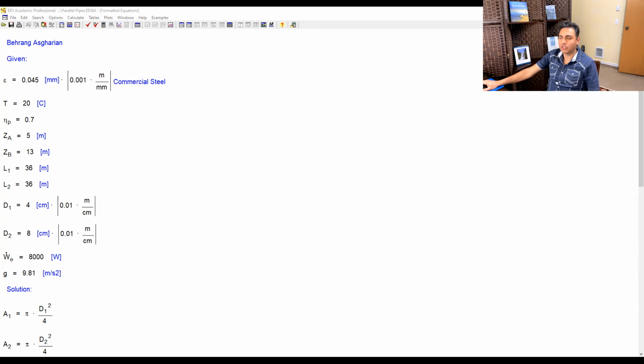That's maximum. You never get friction factor 10 or 11 or 15 in turbulent flow. In laminar flow, you can get a value like that, but never in turbulent flow. That's crazy. That never happens, right? So you use your intuition. How? One more time, I'm going to show you that intuition I'm talking about, because I'm going to share the